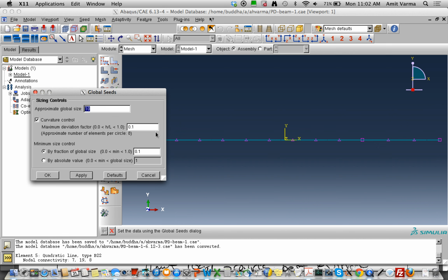Even for elastic analysis, if you end up having 10,000 degrees of freedom, it takes a lot in terms of implementing the solution strategy. Let alone you introduce now nonlinearity. Now these equations are coupled. How do you solve them becomes the solution strategy. So there's a reason why I'm using Abaqus in this class, or I use Abaqus for my work or for my research. It's because I want something that has robust solution strategies. I don't want to be running around trying to figure out what solution strategy am I going to implement.